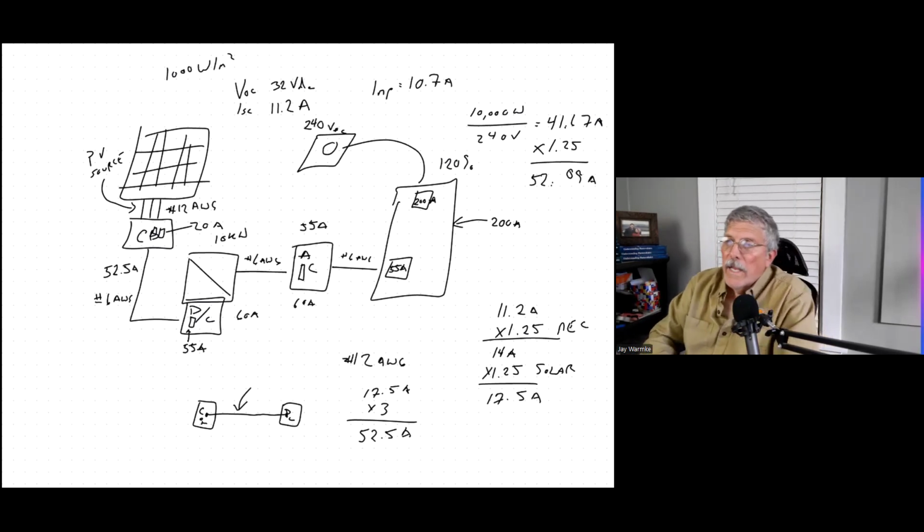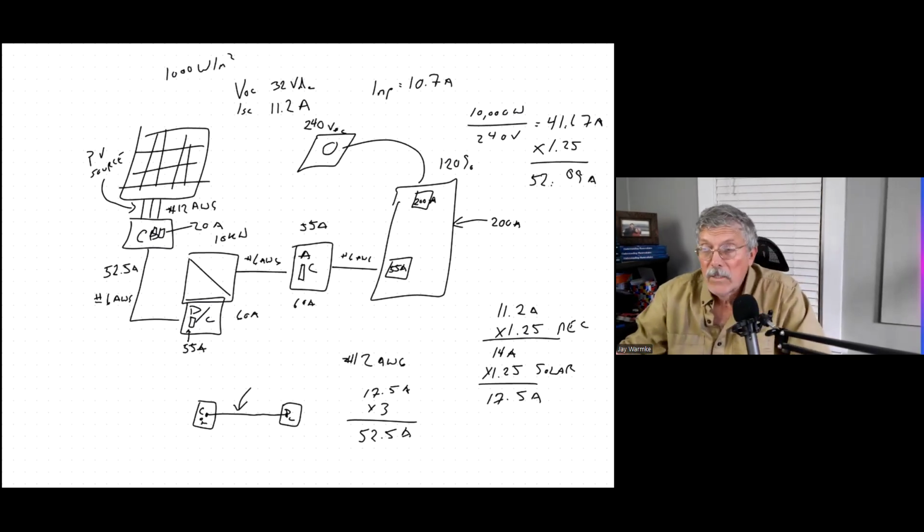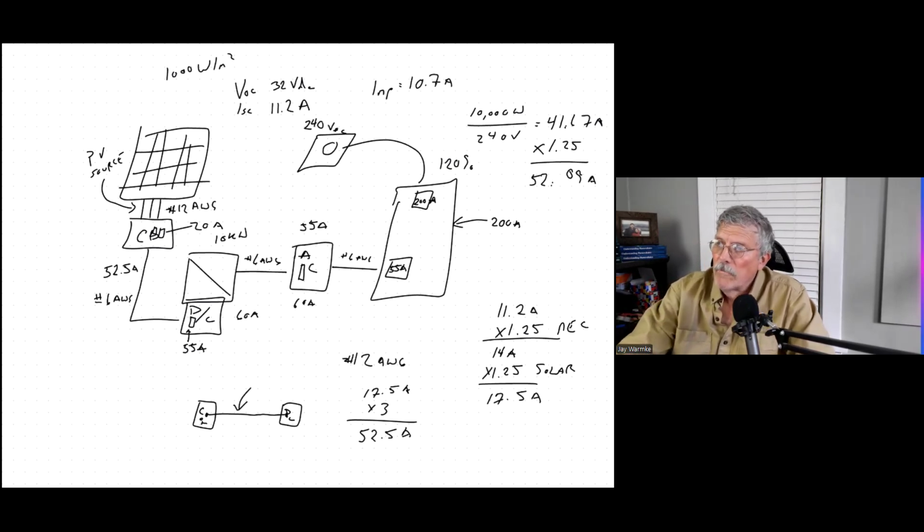You might think that you've already met all of the capacity of that box. But the NEC allows us to go to 120%. 120% of 200 would be 240. So we could actually come in with up to 40 amps of power into this second breaker and not violate the National Electrical Code.